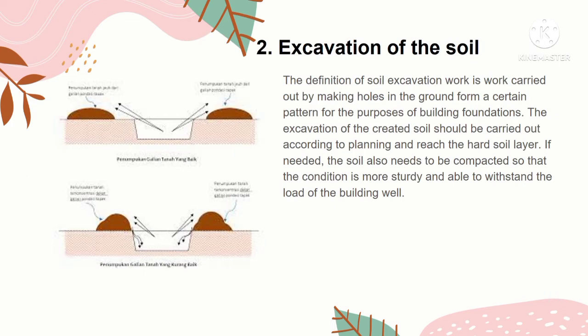The second, excavation of the soil. The excavation of the soil should be carried out according to planning and reach the hard soil layer. If needed, the soil also needs to be compacted so that the condition is sturdier and able to withstand the load of the building well.